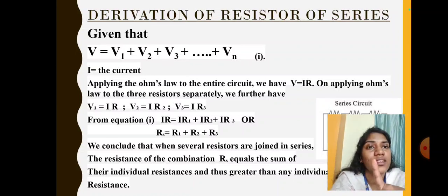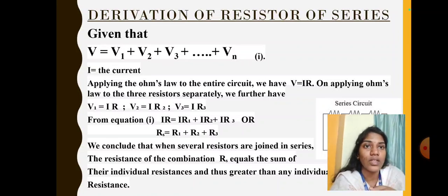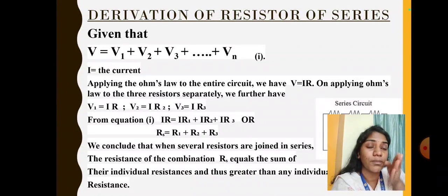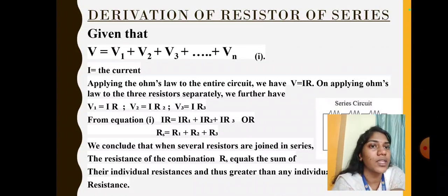If one resistance malfunctions or does not work properly, or a short circuit or anything of the sort follows, the entire circuit does not get the current supply. That is, the circuit is broken down and there will be no passing of current. For example, if the third resistor is damaged or malfunctions, then the current passing from 3 to 4 gets stopped and breaks, so the circuit is incomplete, right?